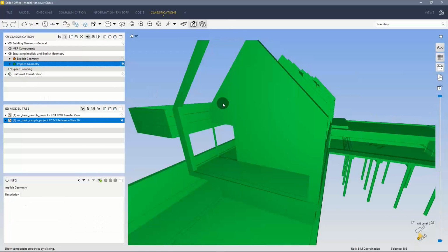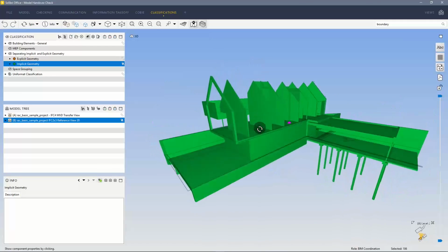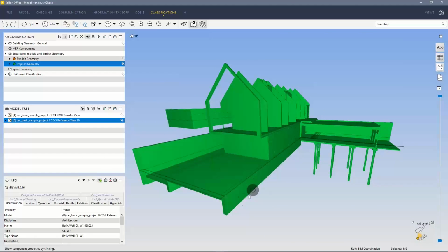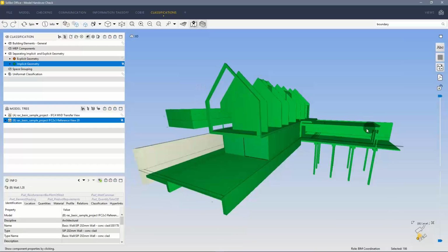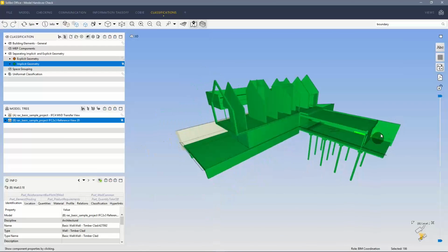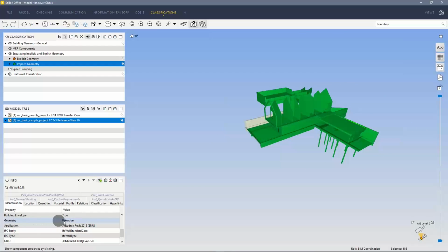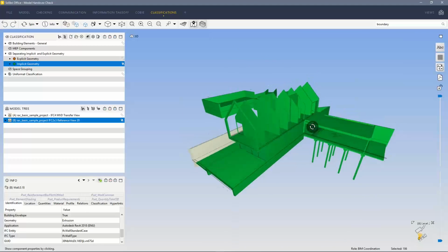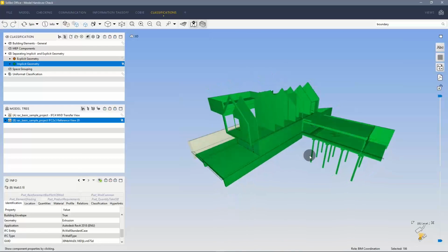At the same time, the good news is that all of these other elements I've got in here, and that's the majority of them, have been passed on from Revit to IFC with actual implicit geometry, meaning that these elements here will follow an extrusion. You can tell those because they are called extrusion geometries within the information panel inside Solibri. So this just gives you a quick overview of the potential of the model once you bring it into your Archicad file.